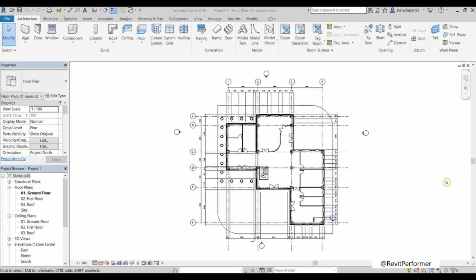Every category in the family library has a tag. Some tags automatically load with the default Revit template, while others you need to load. If desired, you can make your own tag in the family editor by creating an annotation symbol family. I have made my own tags for this project. This is something that we cover in the intermediate course. The reason being is the Revit tags just aren't up to scratch. They don't display a lot of information, and so you won't get the full benefit of using the tags.